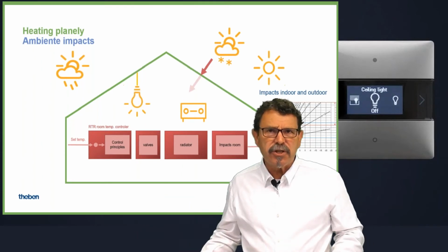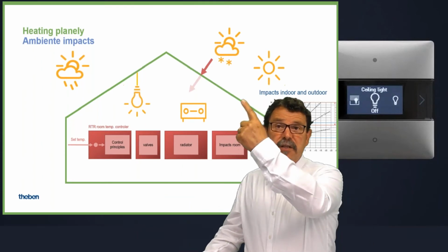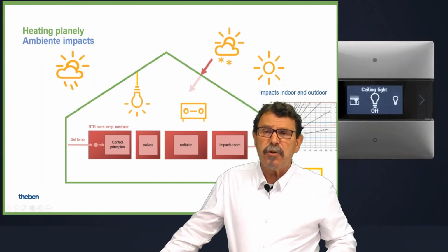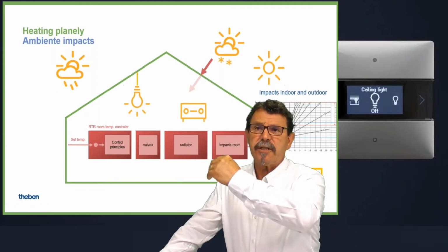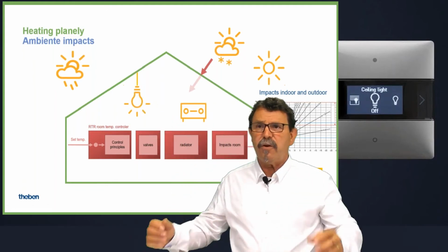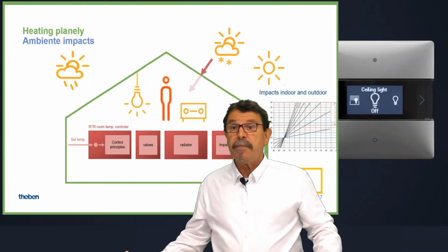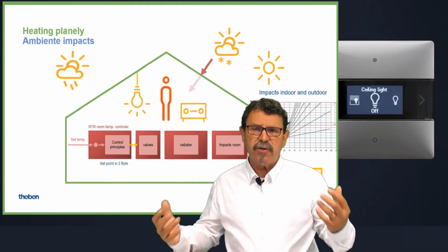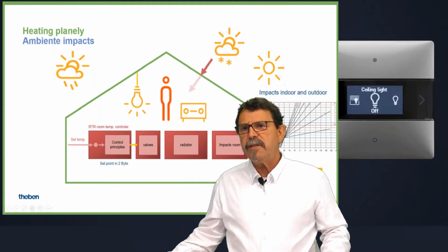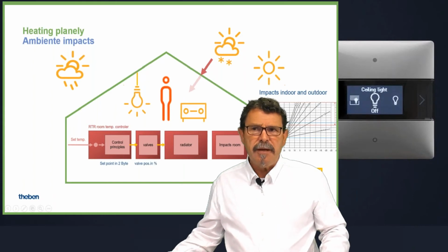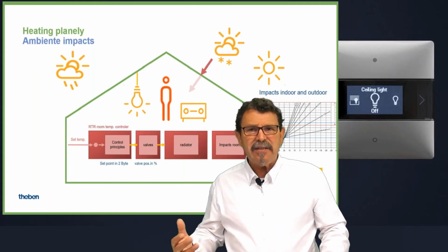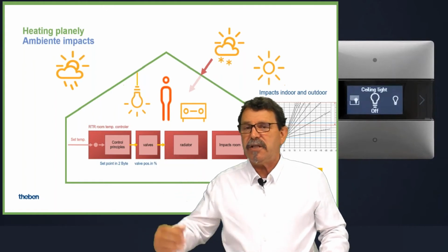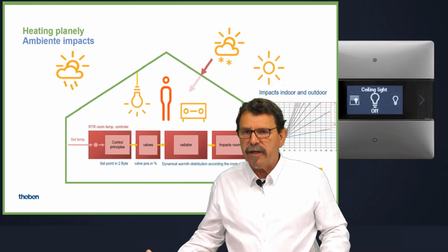This is the weather condition, for instance, always related to the insulation of a building itself. Then we have internal sources, like electronic devices, the warmth of heating, and people walking and working inside, which give a certain warmth into the room. All this is measured by a room temperature controller, which calculates the situation inside, how the temperature is, and what the preset base temperature is that we want to have.